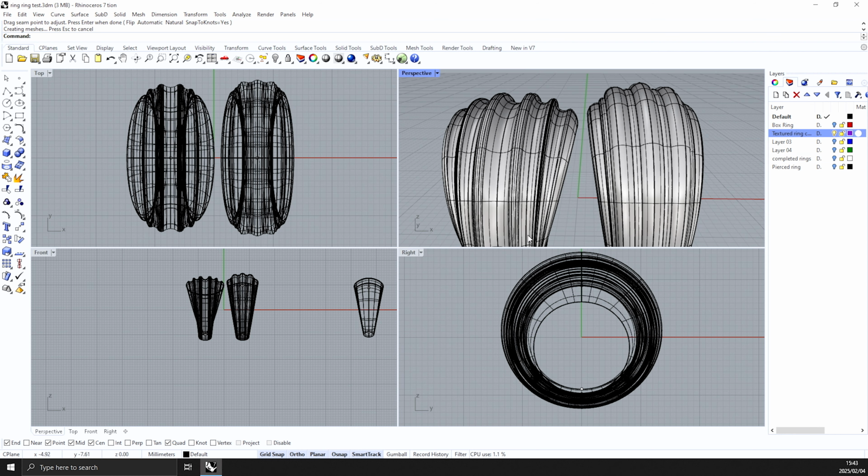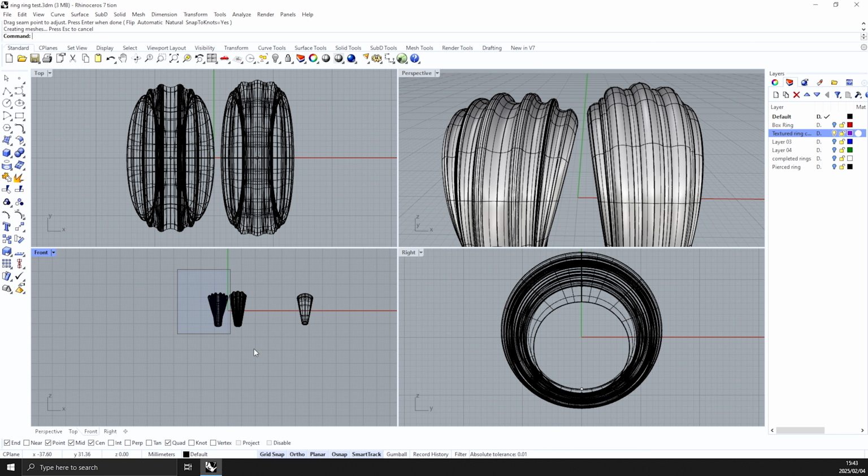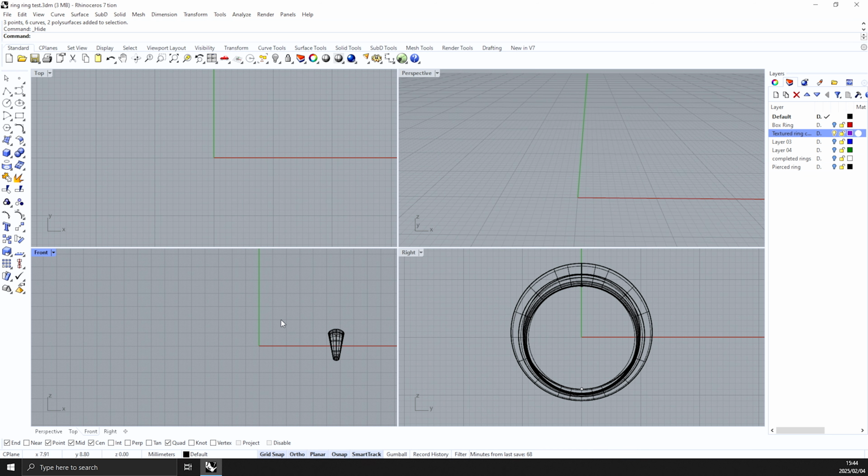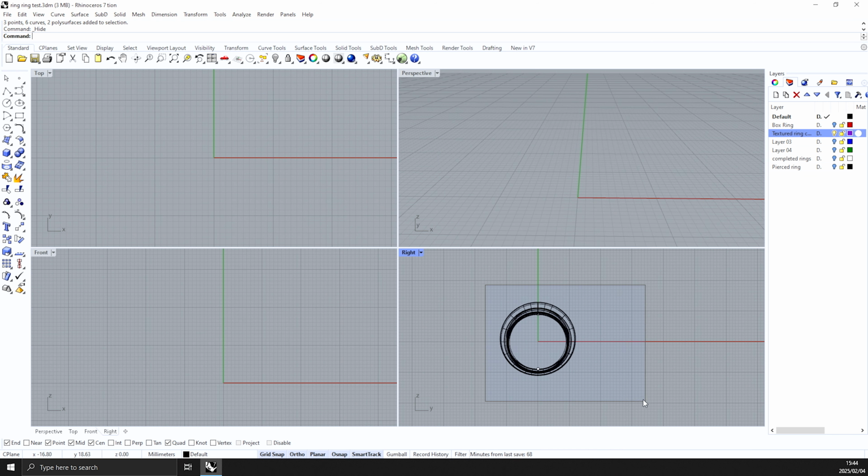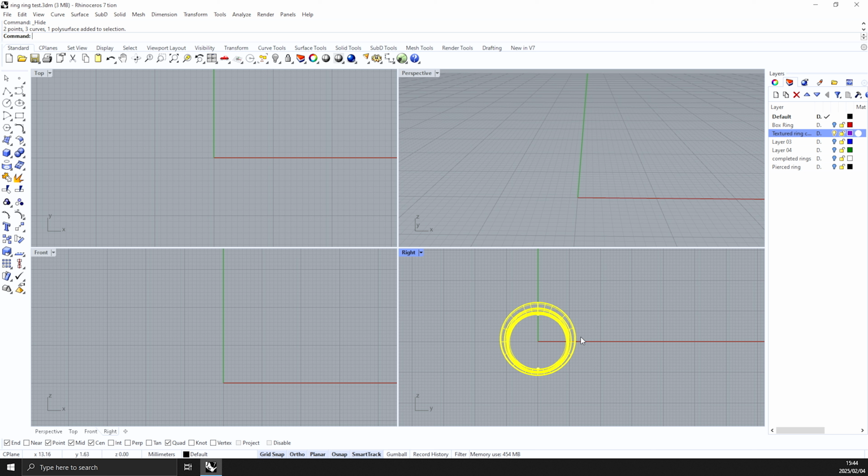So how do I draw a profile like this? It's reasonably easy. I'm just going to go ahead and hide those guys again, and hide that guy for the time being. If you want to hide something, the shortcut key is Control H, or alternatively, you can click the little light bulb there that is turned off and it'll hide it for you.